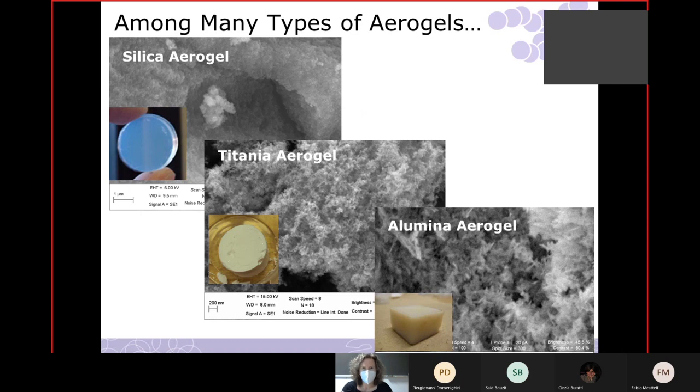In scanning electron microscopy, you're sending electrons to the surface to do the imaging. If you have a conductor, those electrons can be sent to ground. If you do not have a conductor, you end up with the electrons becoming trapped at the surface. Subsequent electrons are then repelled by those electrons, and it's a problem known as charging that makes it difficult to image them.